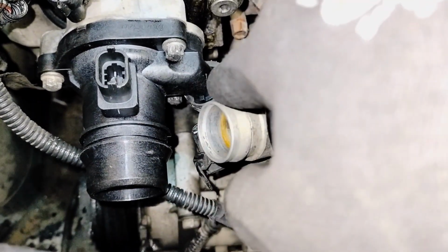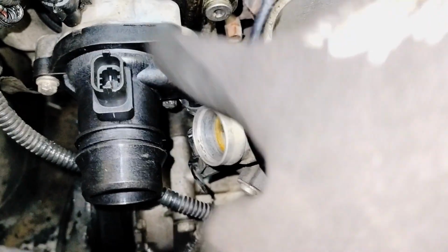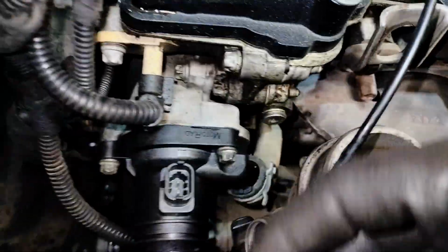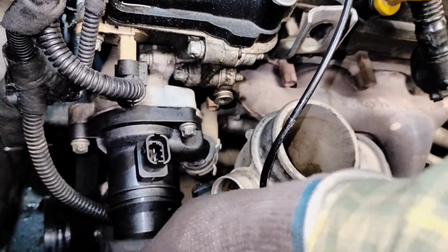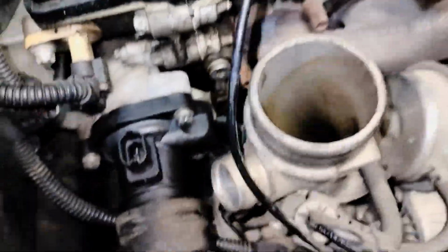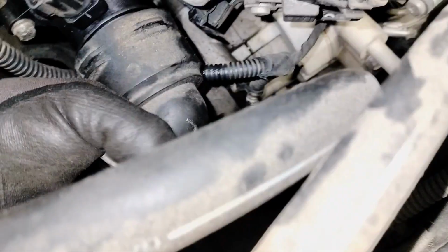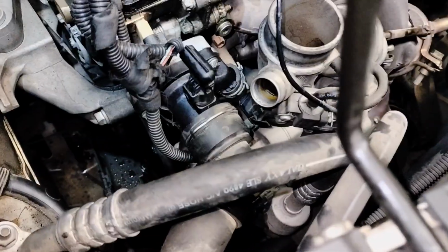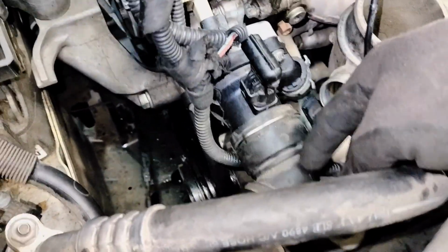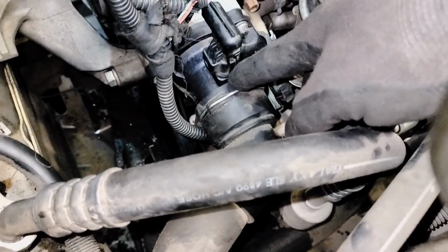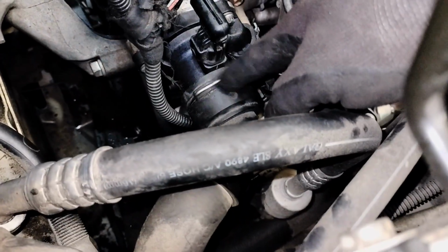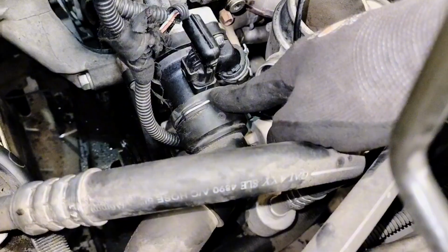So now we have the bottom hose clamp on. We have the 3 bolts. Now we're gonna go with the bigger hose here and install that in there. On the thermostat, the bigger hose, the upper radiator hose, you're gonna know that it's all the way up once this plastic is against the thermostat temperature sensor. And don't forget to install your clip.